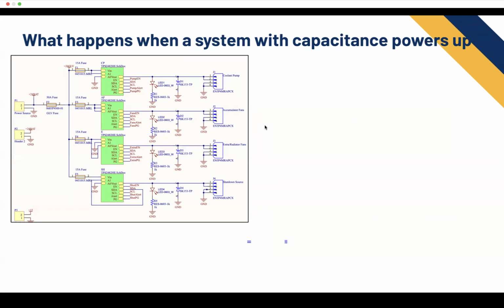This is the low voltage power distribution board, like top level schematic in the schematic tree. So as you can see, we get this power source over here on the left. That's our low voltage batteries. And then we have our grounded low voltage fuse, which is required by the rules. It's the first thing that the battery power goes to, so that if too much current is pulled, it burns.